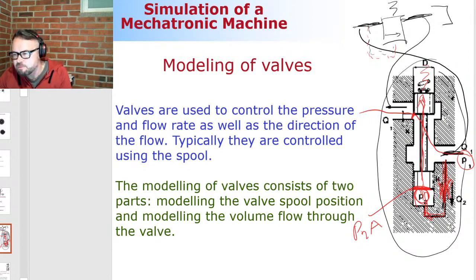Okay. Now, to be able to do this, first thing and the first step that is extremely critical is that we have to have some kind of prediction. How is the spool position? And that's what takes us like a philosophical discussion about how is a modeling of hydraulic components. We could, in theory, model the spool position such the way that is fully physics-based. Fully physics-based, meaning that we will take everything into account, including the mass of the spool, pre-tension of the spring, flow forces, pressure forces, so on and so forth.